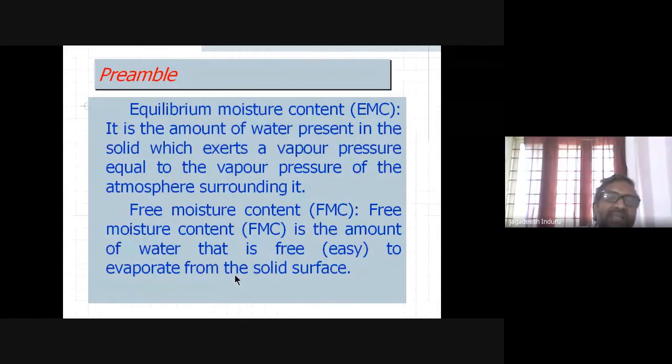What does it mean? In the drying process, when you are handling equilibrium, for whatever hygroscopic material, immediately after drying you need to put it in closed, tightly packed containers. In that case, your drying will be purposeful. So it is very critical; simply drying is not sufficient. If it catches the moisture again, your attempts are gone.